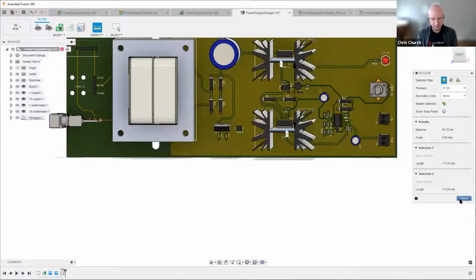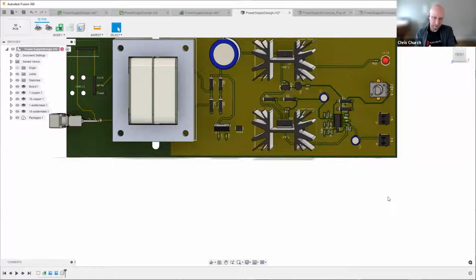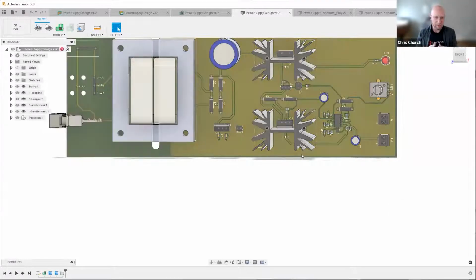So this is something, by looking together at this design and thinking about the manufacturing process, we can look at that and say, for a more repeatable build, we want to turn that bottom, the heat one, around so that the screw is coming in from the outside, so that we can use a very standard process of just coming in with a screwdriver and attaching those. It's going to be lower cost, it's going to be faster, it's going to be more reliable and less likely to damage that board. Excellent.